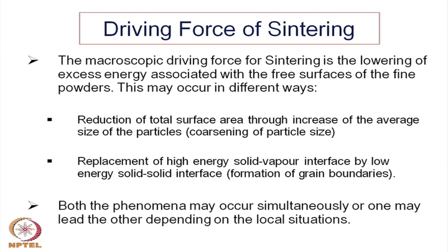The other possibility is the replacement of high energy solid vapor interface by low energy solid solid interface formation, and that is nothing but what we call the formation of grain boundaries. That means the particles or the fine powders, when they are free, they have a surface area, and that surface is nothing but the solid to vapor interface, that means with the air in this case. Or one can say solid gas interface.